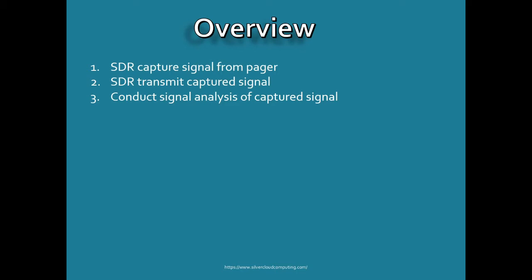And then once we determine what the bit pattern is, we'll go ahead and use Audacity to actually look at the bit pattern, and then we'll use GNU Radio Companion to synthetically generate the signal. So we won't need a captured file to play back. We'll actually have GNU Radio Companion generate the signal for us.